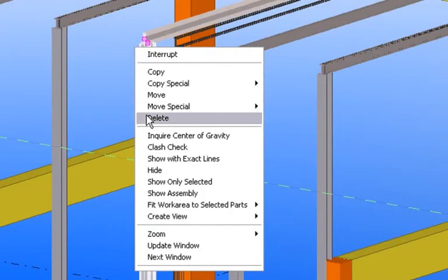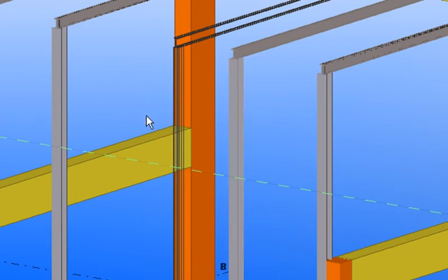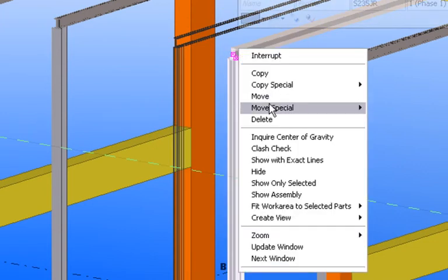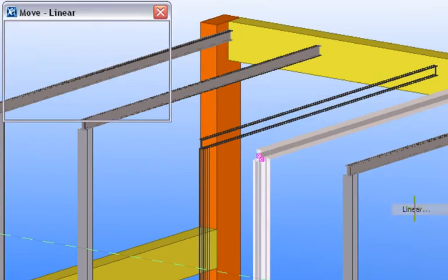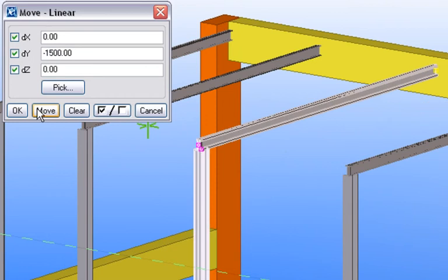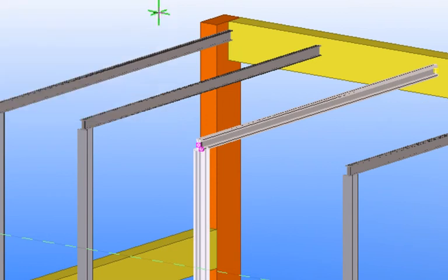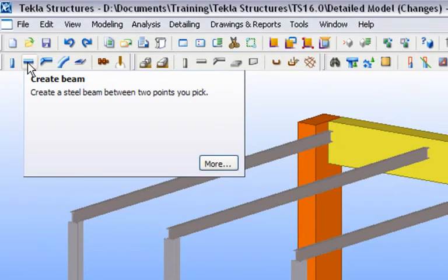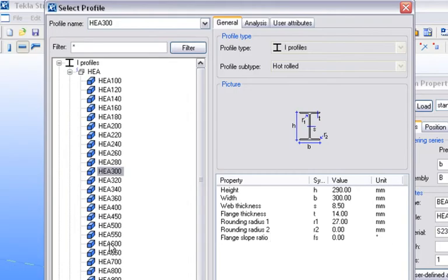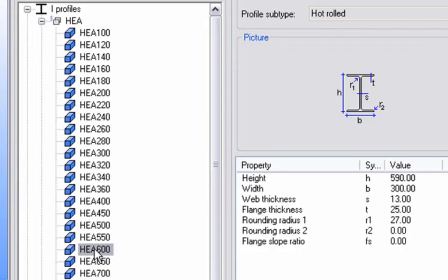First, we will delete the middle steel frame in the structural model. Then, we will modify the position of the other steel frame. The new position of this frame will be based on the frame in the architectural reference model. Finally, we will also place a new horizontal steel beam in the structural project as a suggestion to give the correct stiffness of the modified state.